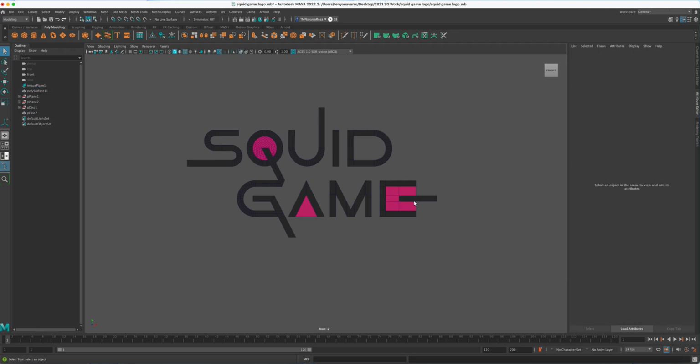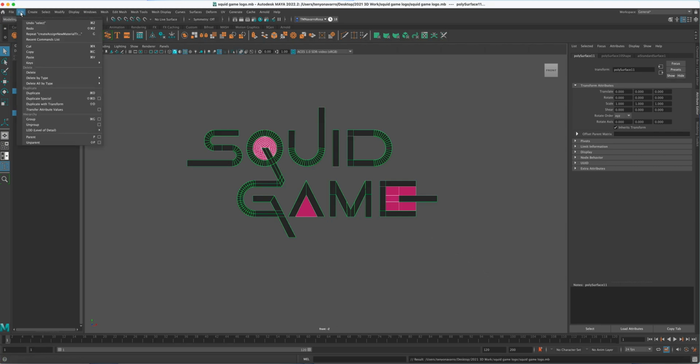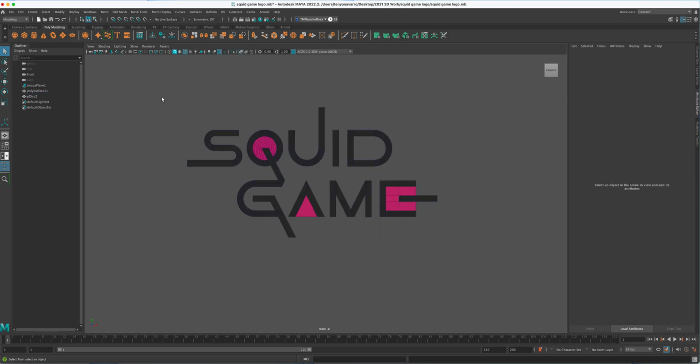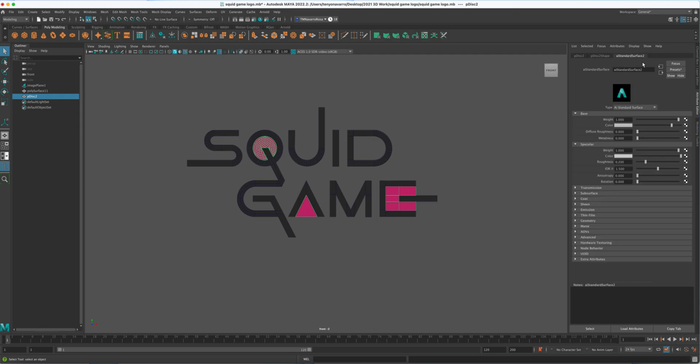Let's hide the logo. And you know what? No. Let's select the pink. We have a lot of history here, so let's get rid of this. Let's Command S. Edit, delete history, non-deformer, freeze, center pivot. So now let's set, before we hide the background, let's make sure we select the color that we want for this. So we're gonna take this, we have a color picker, and we're gonna take that pink here.